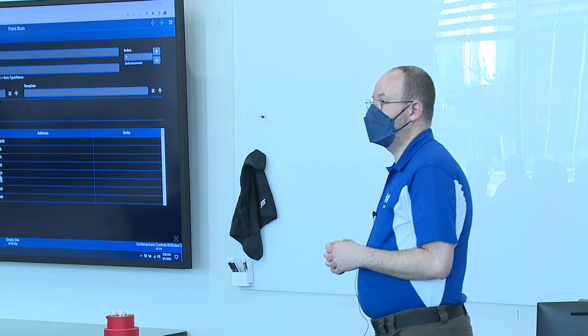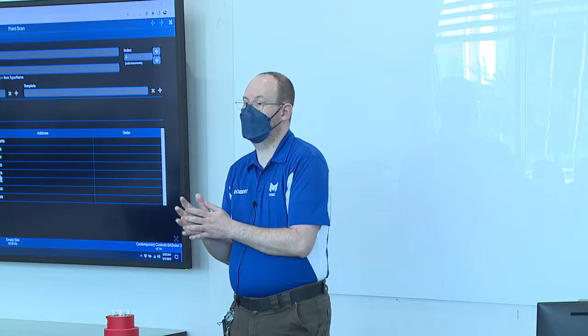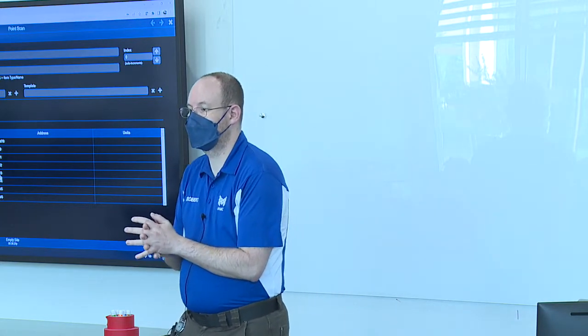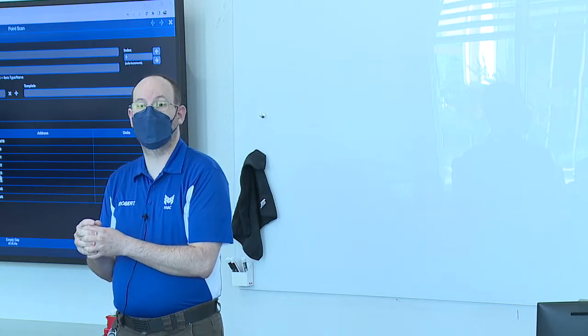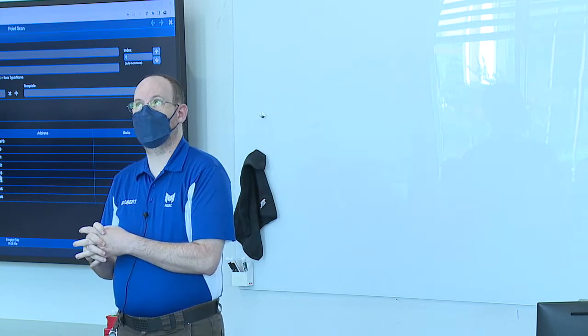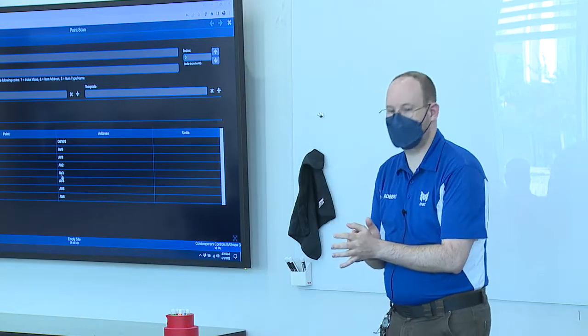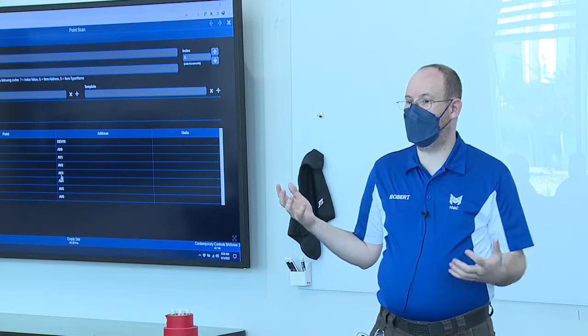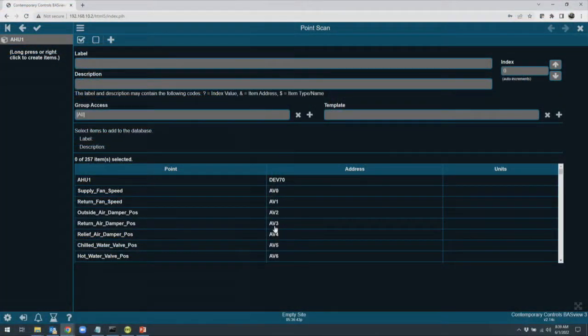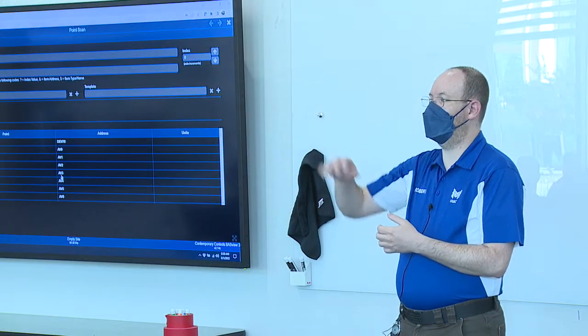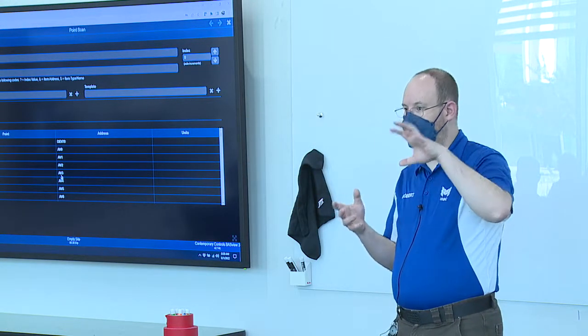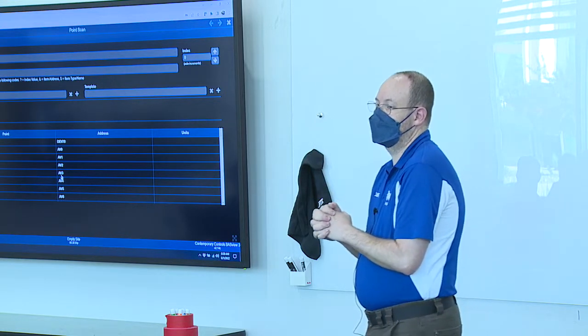And you should find something like 257 or so points on the air handler control. Proprietary object? What's that? Proprietary object scan or the quick scan? Just hit scan. Yep. So there are options on that one. Some give you options, some don't. This one will give you the ability to look for just the regular high-level BACnet stuff or dig deeper for weird stuff. Okay?